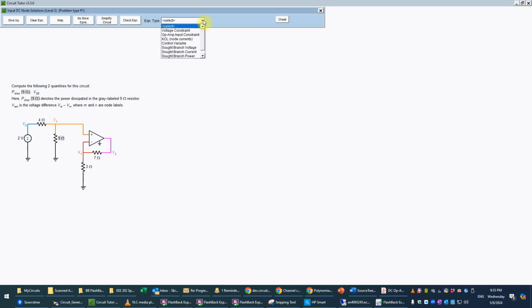So we're going to go ahead and treat this as an ordinary nodal analysis, with a slight modification for op amps. And remember that we virtually always do nodal analysis on op amps because the meshes are not really clear given the internal elements there, and it might even be non-planar. So we're going to do nodal analysis, and we also don't select our ground here as you would normally do, because that's really the fixed ground of the power supplies, which we don't want to try to change.